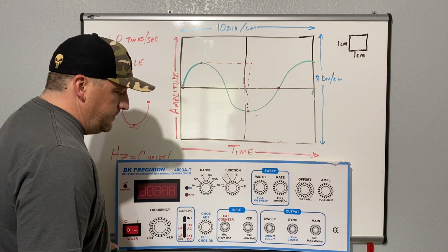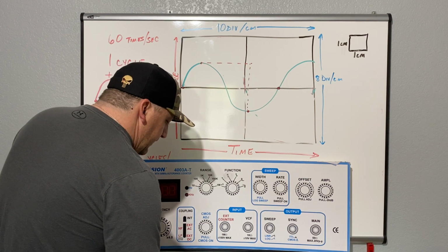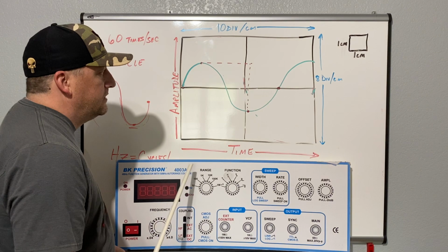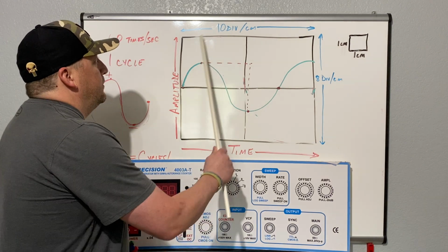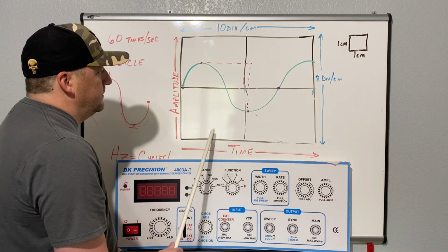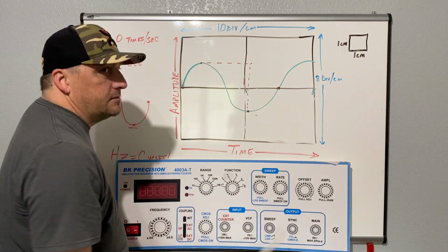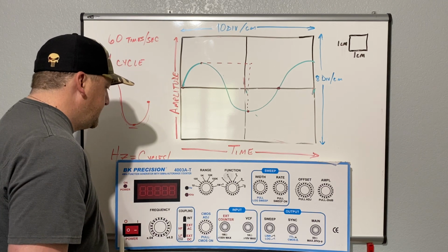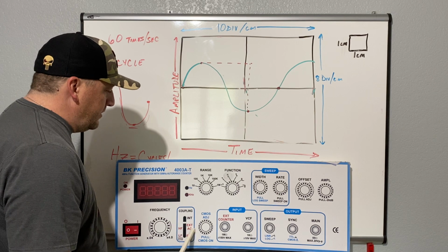4 volts peak to peak. We're going to have a 1/2 volt for each division. That'll give us 2 volts this way and 2 volts that way, and that will be basically a screen top to bottom, so that your signal is tracing from top to bottom, top to bottom, top to bottom. Coupling here, we want to be on external AC.